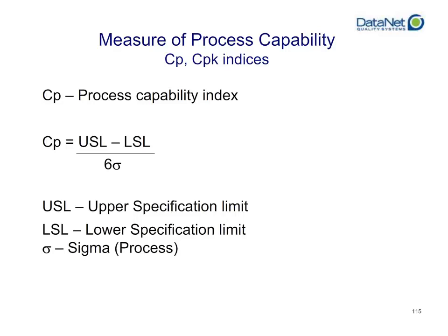How do we calculate CP? CP is your upper spec minus your lower spec, divided by 6 times the standard deviation of the data within that data set. So it is your upper spec minus your lower spec over 6 sigma.